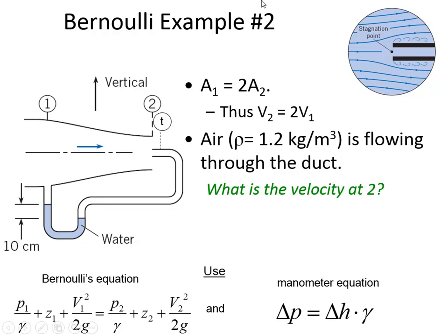Now here in this example, we're measuring the pressure. Here it's going sideways to the flow, but then the end of this is actually intercepting one of the streamlines. If we zoom in on what's happening with that tube, the air is flowing sideways and there's a stagnation point.